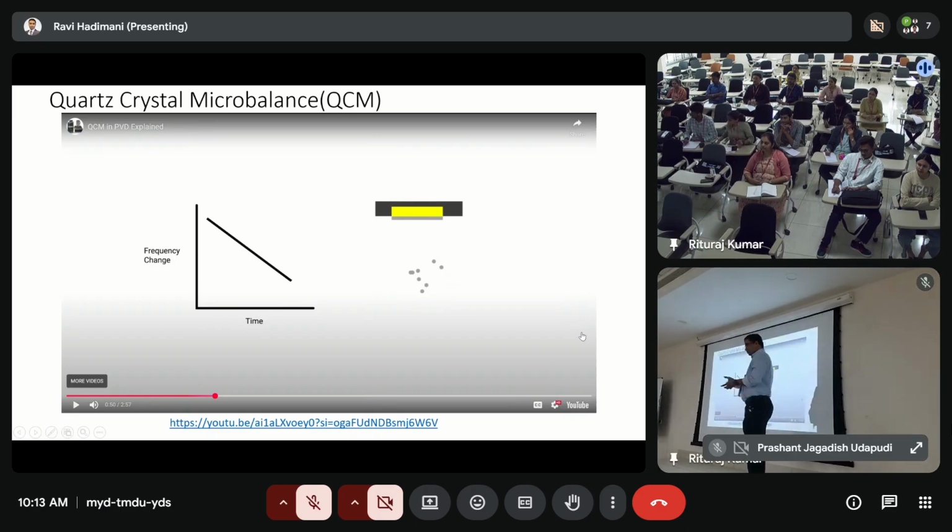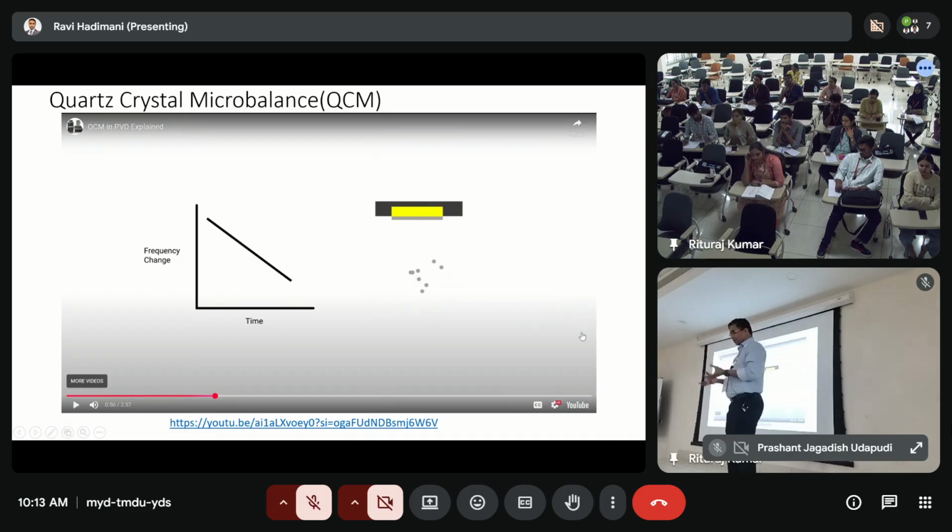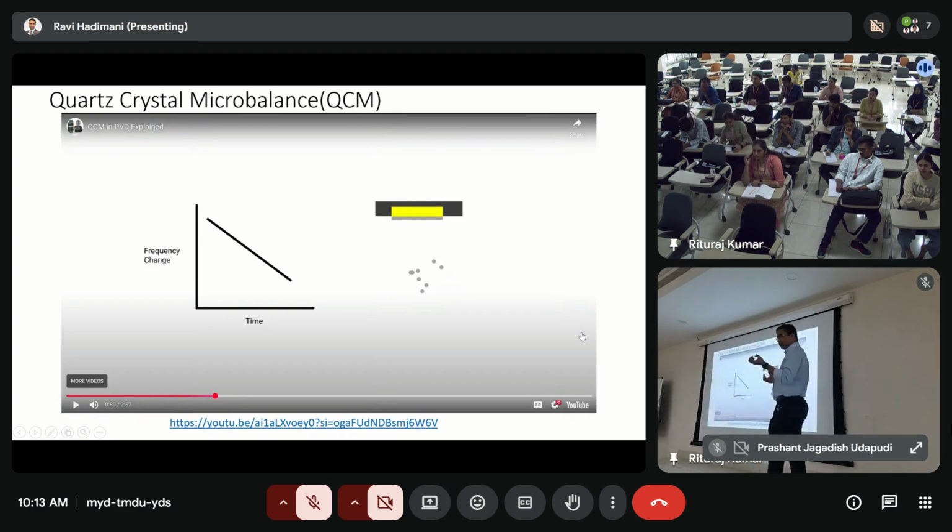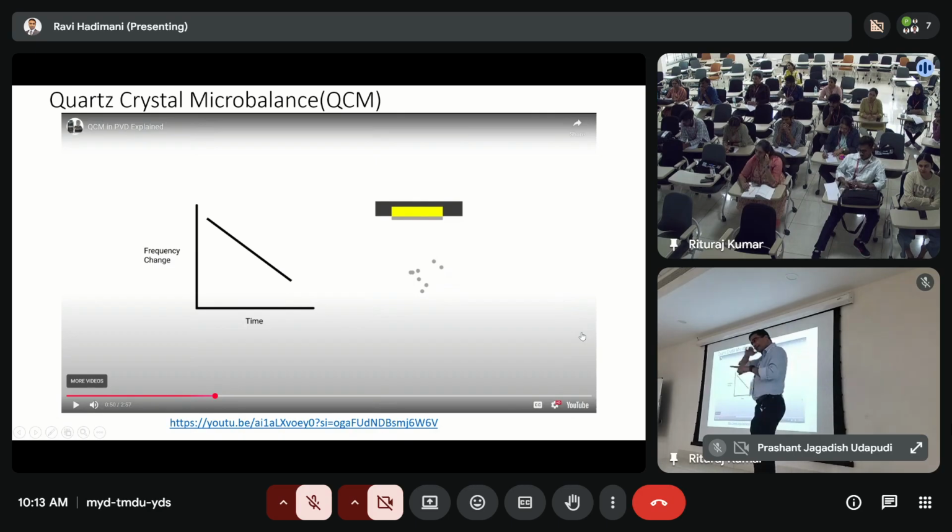And we don't have good control over when you start, for both e-beam evaporation and thermal evaporation. Because once you heat, the atoms start to get ejected from the surface, and you can't control that because it is a difficult process to control. But what you can do is put that shutter on top of the target, so whatever vapors are coming do not go to the substrate. But when do you want to press that shutter?